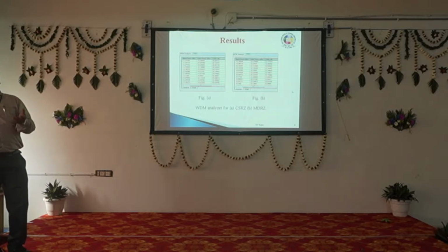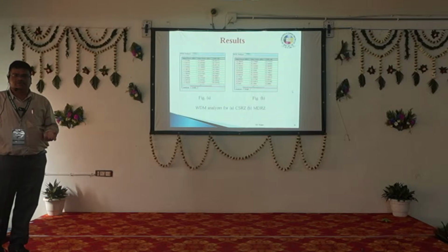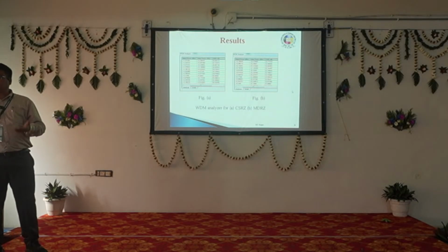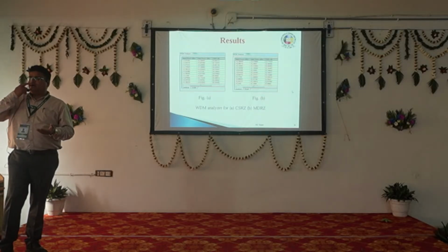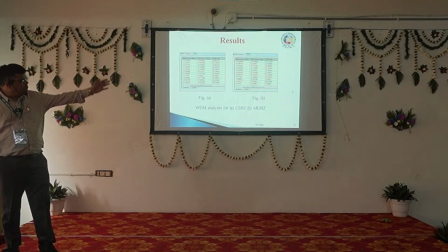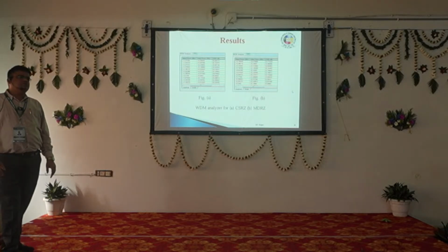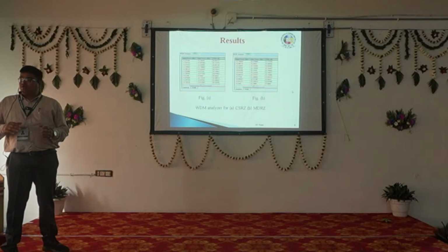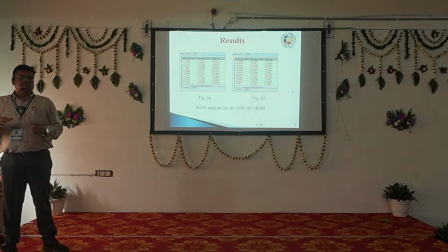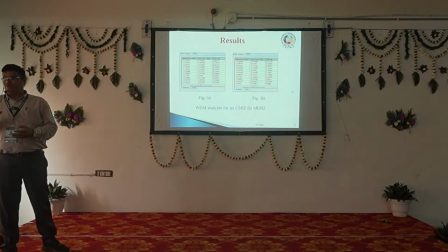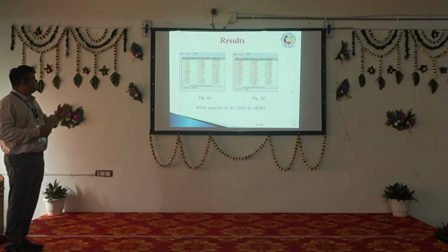And why it is, you can go into detail. But what I mean to say is, by using different modulation techniques, we can minimize the nonlinear effect, we can minimize the dispersion, we can minimize the turbulence. So that is why we are getting better OSNR. Are you getting it? That is why a lot of advanced coding, advanced modulation and hybrid modulation techniques are being developed for minimizing the effect of the channel. And if the effect of the channel is minimized, definitely OSNR will improve. OSNR will be better. Next please.